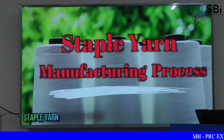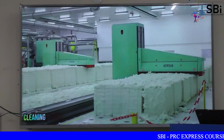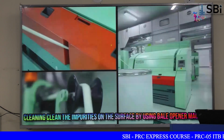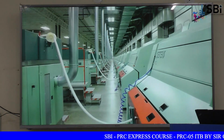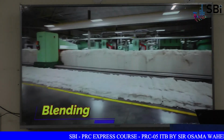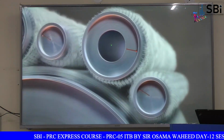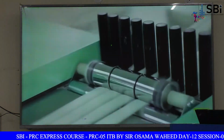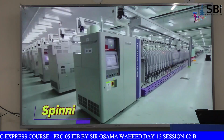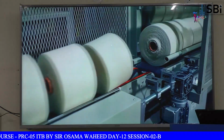The process of staple yarn manufacturing starts with opening the bale of fiber and cleaning the impurities on the surface by using a bale opener machine. Then processes are followed by a series of continuous operations such as blending, mixing, carding, drawing, roving, and spinning. And finally, we get the cones of yarn, which is used to make fabric.